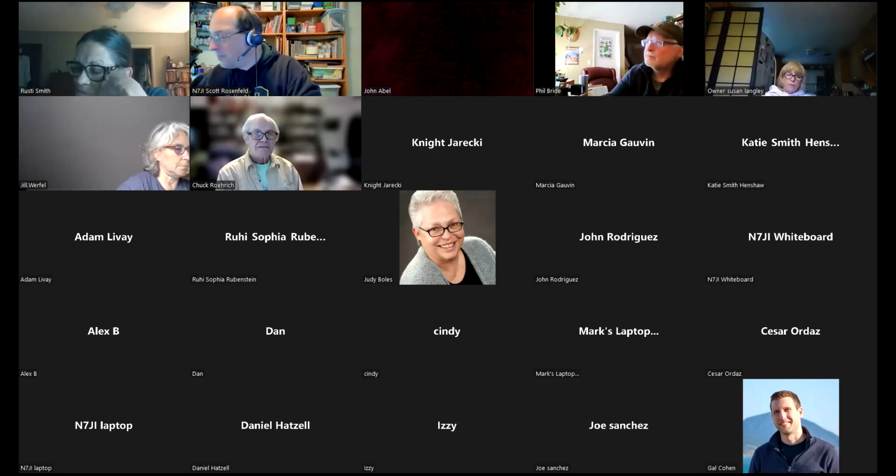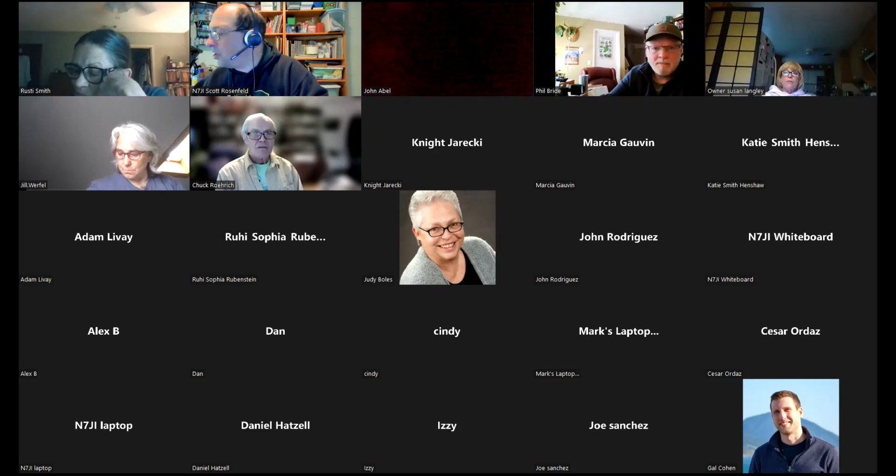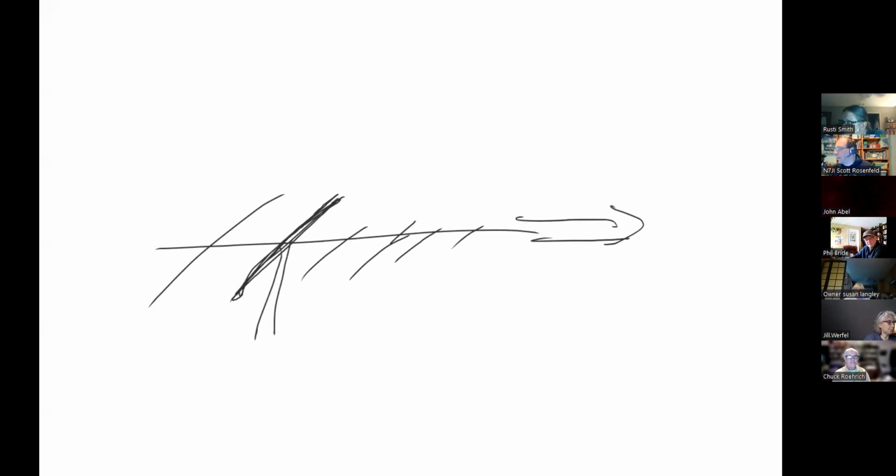Okay, a beam antenna is an antenna that concentrates its energy in one direction. So this would be known as a beam. This is actually known as a Yagi, named after one of the two inventors. The other one was Uda. So this is a beam antenna, concentrates its signal in the forward direction. At its core, right here, this is an antenna that looks like this. What does that look like, everybody? Looks like one of those Arrow antennas that you would get. No, but this section right here in the middle, that's a half-wave dipole.